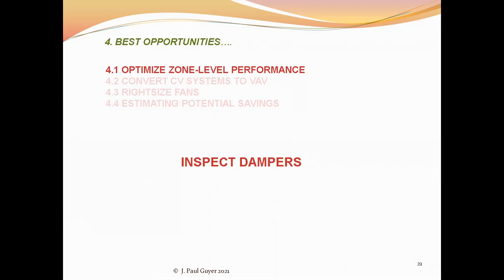useful. In older buildings where maintenance has not been rigorous, it's likely that some of the zone dampers are frozen in position, rendering them ineffective at regulating comfort.